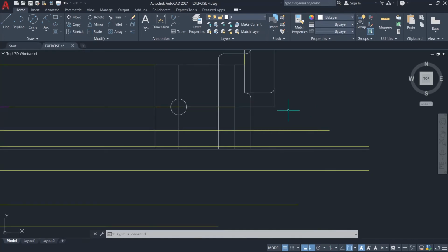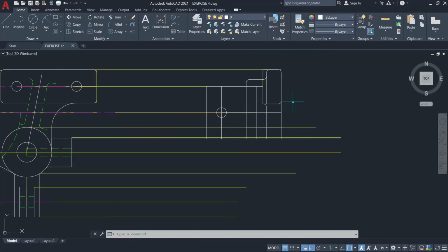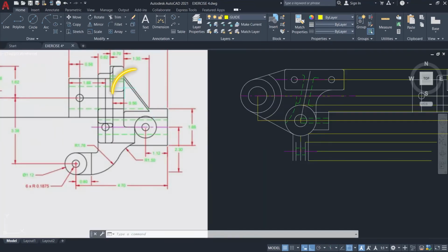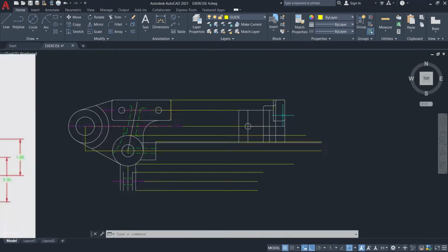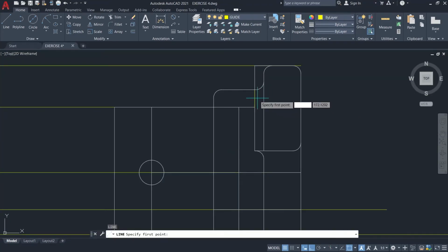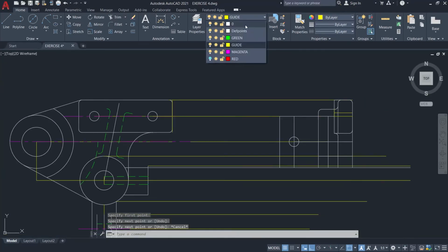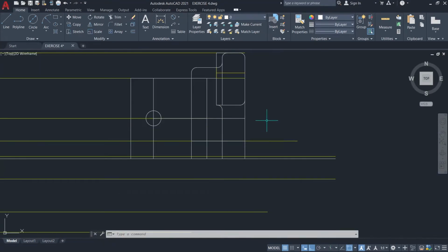To continue, extend this line up to this set line. Make a horizontal line across this vertical line. Then, to create this oblique line, create a horizontal line from the midpoint and lower endpoint of our previous guidelines. Then from the endpoint of our midpoint guidelines, connect it up to the fourth yellow guideline we've made earlier. Then, to create another oblique line, make a line measuring 2.1237 with a degree of 308.